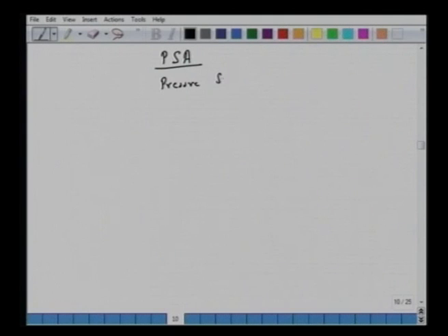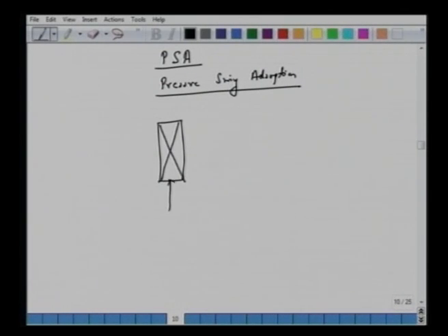So, pressure swing adsorption. In the previous class on adsorption, we had a very brief introduction on this. Now if you have one bed of solids and we bring air containing, say, carbon dioxide in nitrogen, and treat this here, the concentration of CO2 will be very small at first, but slowly this bed will get saturated, the concentration will pick up, and now we have this breakthrough curve.